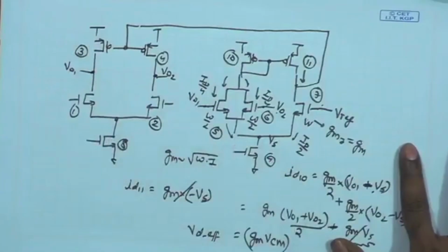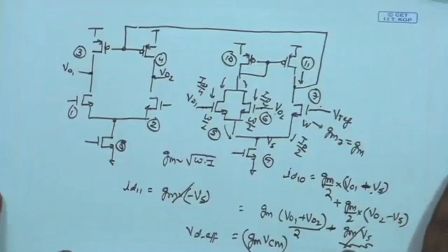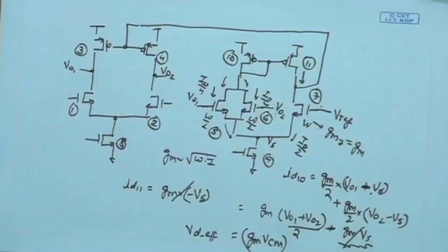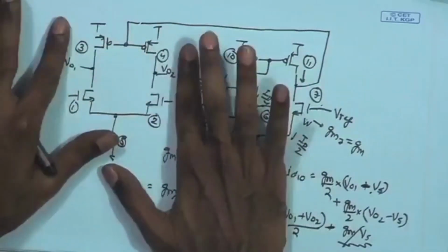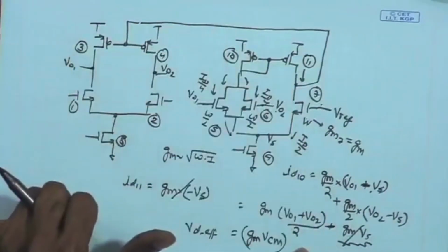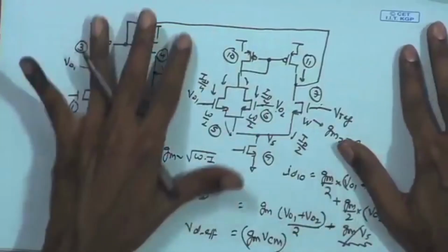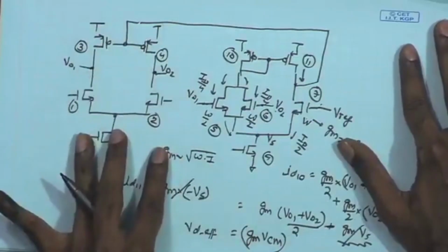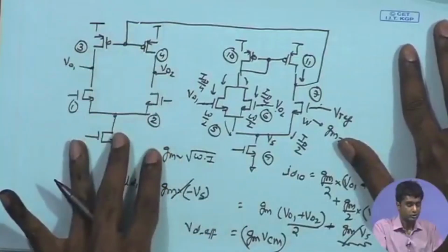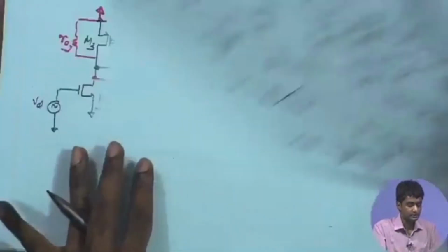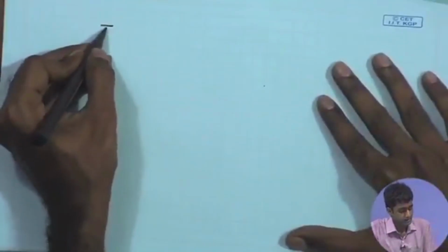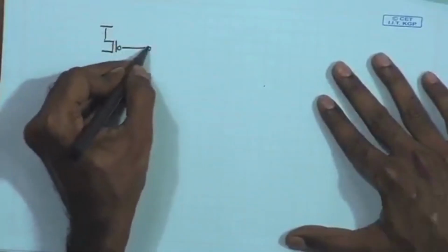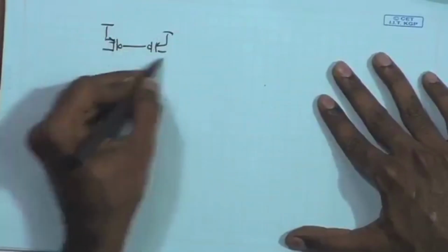Now, in general, when we go for operational amplifier design, we know that we will be needing multiple stages. We will need 2 stages in a given operational amplifier at least to get a larger gain, and the second stage is also active load and fully differential. So, how do we incorporate common mode feedback in such a case? So, we can look at that scenario where we have a fully differential op amp with 2 stage amplification.